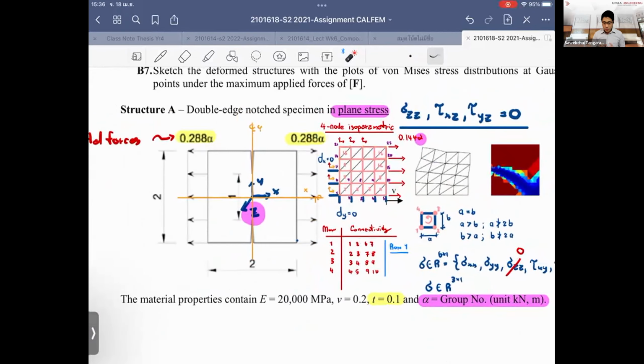Okay. When we're looking at this, the question that you have next is what you should do, right? So you already constructed the mesh and so on, then you need to look at the formulation. The problem they ask, before we go to the formulation, is that according to the law that we have here, the unit is kilonewton meter, so you don't confuse the unit, right? You have to transform everything to kilonewton meters, including the thickness. I use 0.1 meter, which is 10 centimeters.